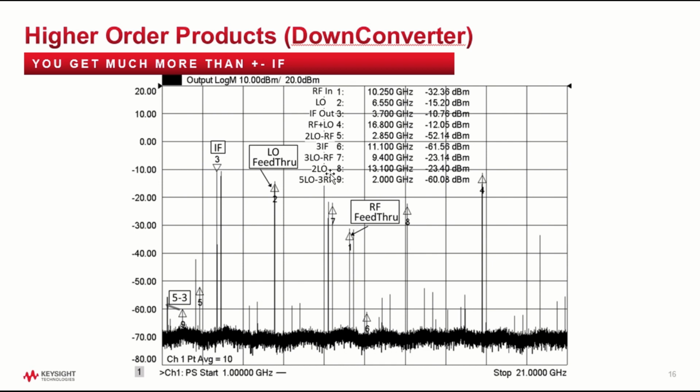And number 8, that's 2 times the LO. It doesn't move at all. And then the RF plus the image signal, which is the plus signal, you can't really see it because it's hidden behind this graticule line, but it shifts down 1 when the RF shifts down 1. So it's moving in the same direction as well. So because both of the outputs, the LO plus and the LO minus, shift in the same direction, we would say this is not an image mixer.